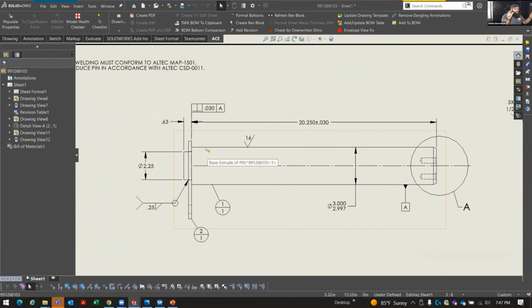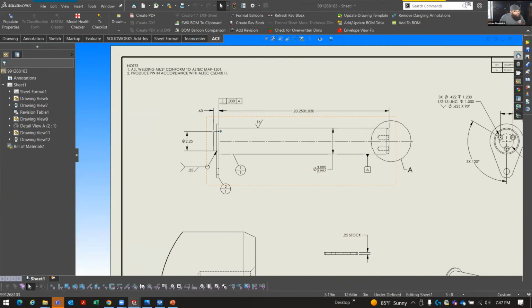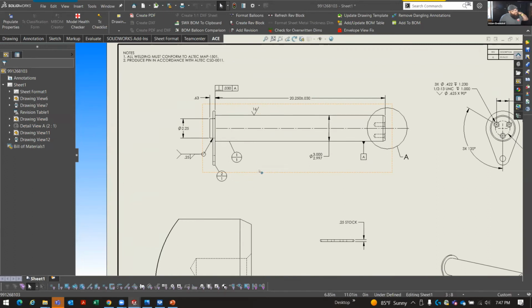It only has 2 engagement points that are 4 inches total, so 2 inches on each side. Do you think I need to keep that much of a tolerance over the whole length of this 20-inch pin at that surface finish? This is a $600 pin currently. Well, it's only the two ends that actually touch. There's two bearings at the ends. That's it. The inner pieces don't need to be there, right?